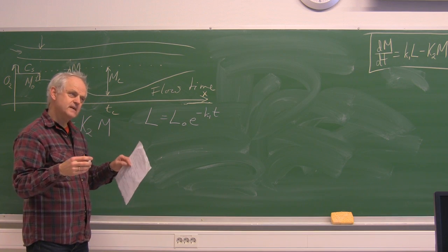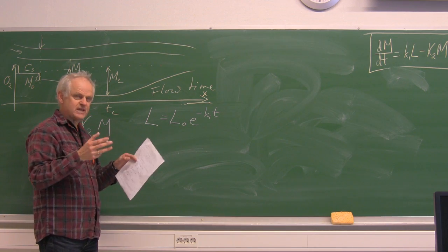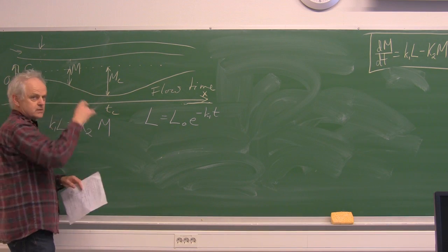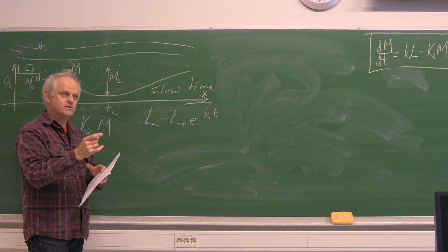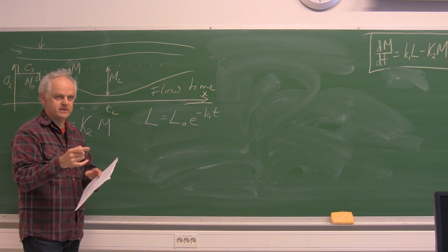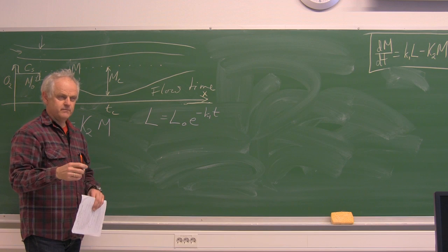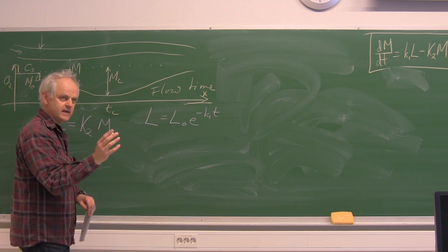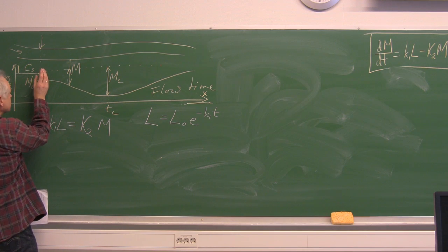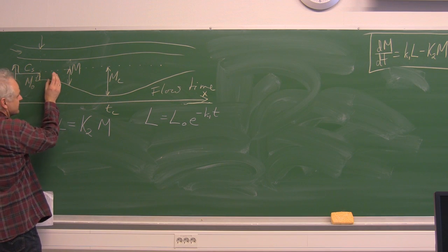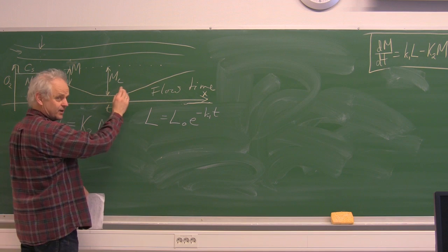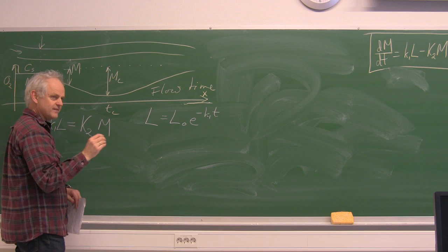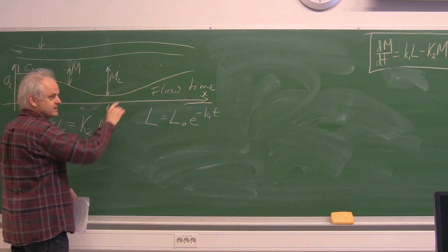So what is the BOD test? Just to take a step back, the BOD test is where you take your discharge, put it in a bottle, and look at how oxygen is disappearing with time. It's a batch test, so it's kind of like a simulation of what's happening here.